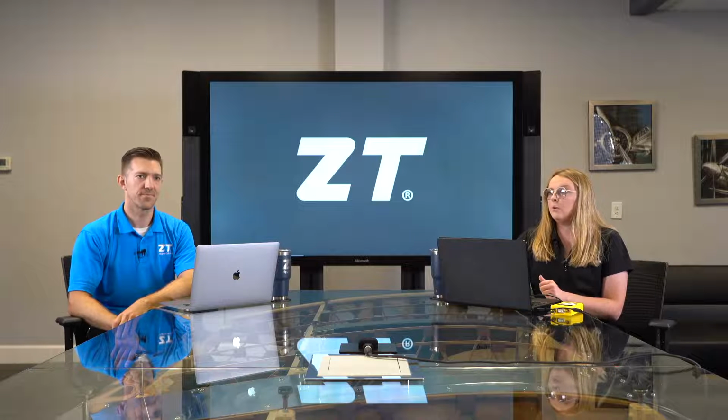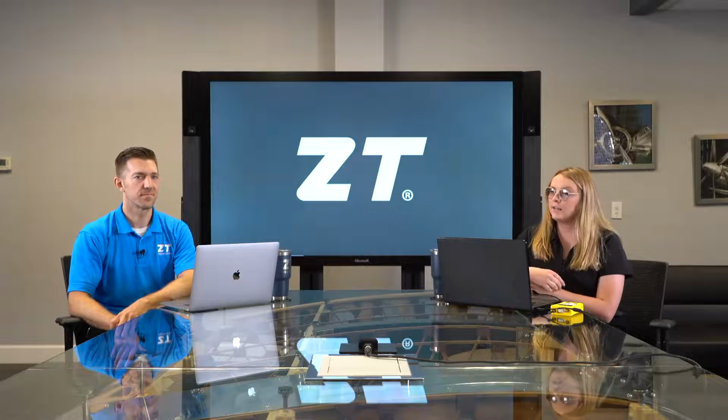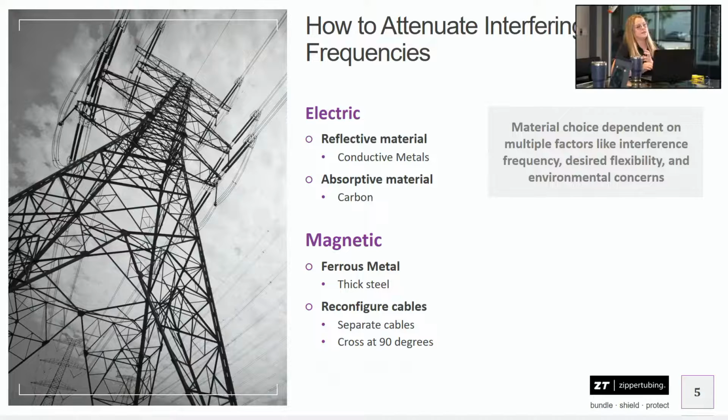So now that we know what we've got, we're going to figure out how to knock down that interference, or how to attenuate that interference. This is going to be dependent on your specific application, depending on what route you take, due to factors like environmental concerns, the temperatures you might be seeing in your system, or possibly chemical exposure. A big one that's going to determine what kind of shield you use is the flexibility you need in your system.